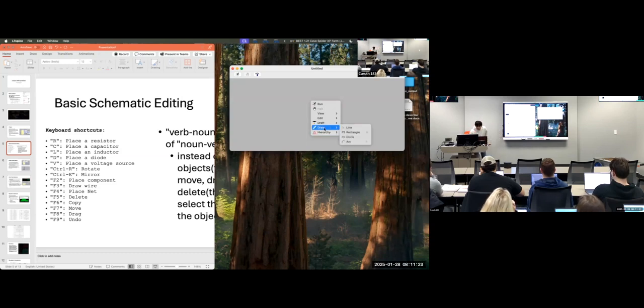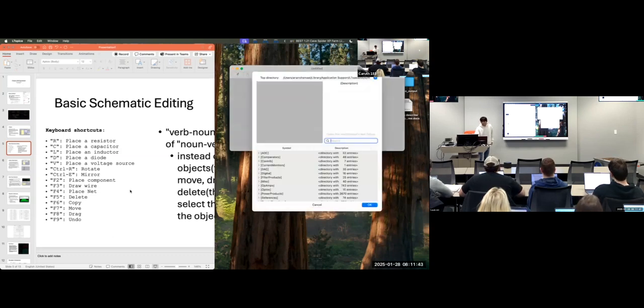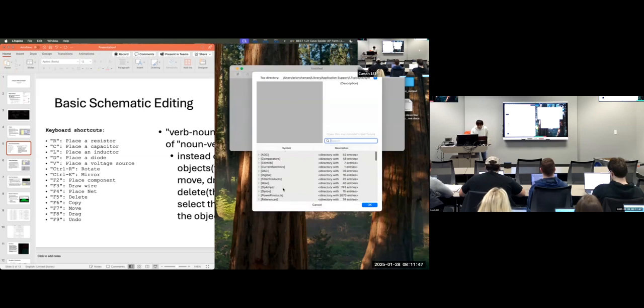Okay, so I'm going to go to draft, and now I have a bunch of options here. I can do a wire, component, net name, spice directive, text, data label, or bus tab. I'm going to go to a component right now. And when you download LTspice, I don't know if you have the option or it automatically downloads all of its example circuits. But you're given this little interface right here with all of these folders and a bunch of stuff.